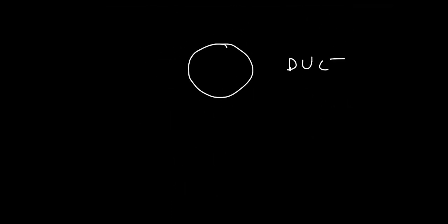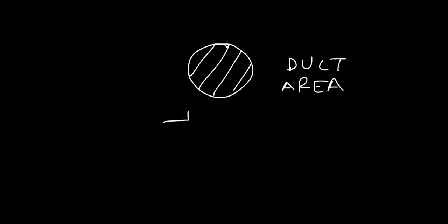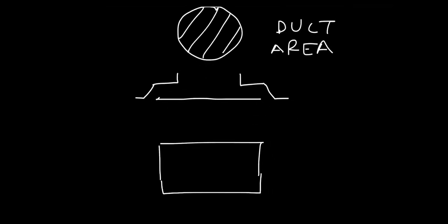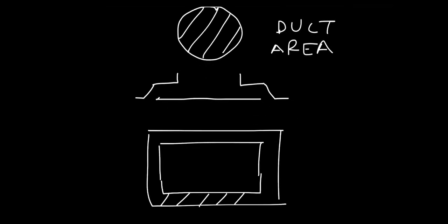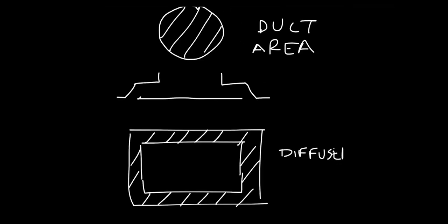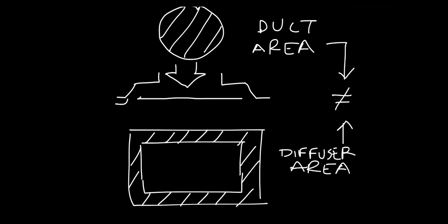Diffusers, unlike grills, have a size and shape of inlet and outlet areas that are generally unequal. The inlet of a diffuser is usually round to correspond with a sealing duct, while the outlet area may be slots or louvers. Unlike grills, the direction of airflow through a diffuser is usually turned at 90 degrees in order to blow a horizontal air pattern across the ceiling.